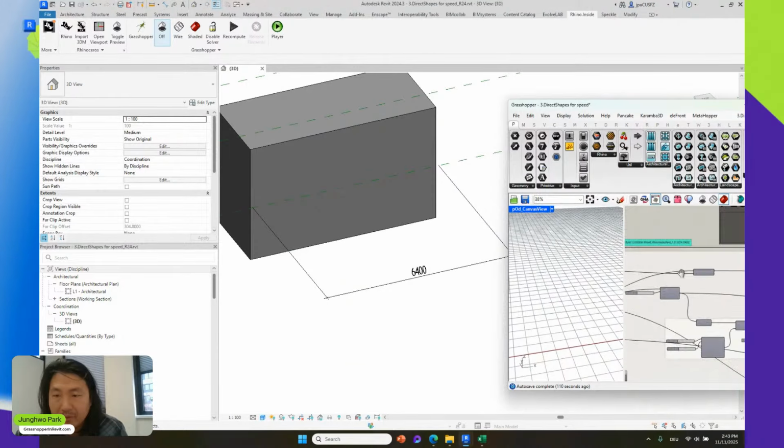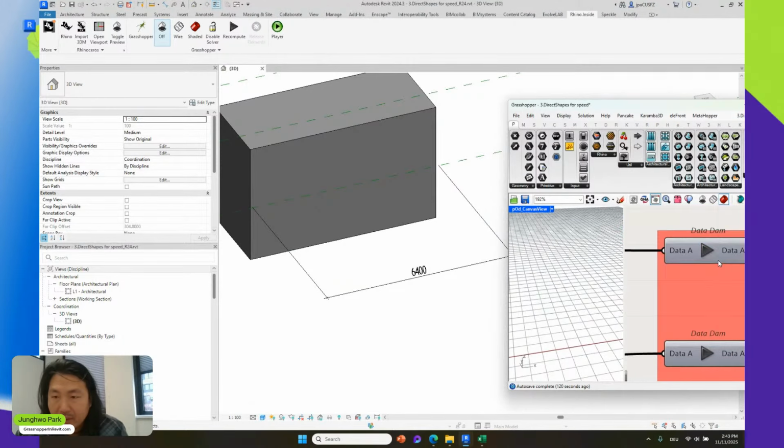and obviously it moved, and I just shoot the data, and as you can see, the dimension also changed. I mean, accordingly it moved the position, translated, but it kept the same information for that element. So this is one of the reasons why direct shape is still powerful, because you don't lose this relationship with the annotation. But sometimes when you really have to flexibly make quick design changes, this really helps you to keep documenting in the early design stage.